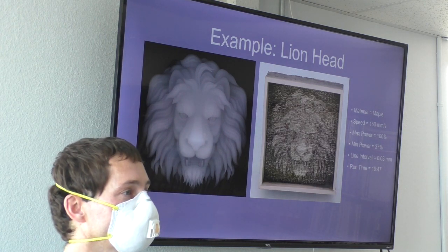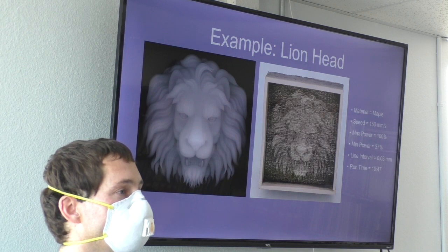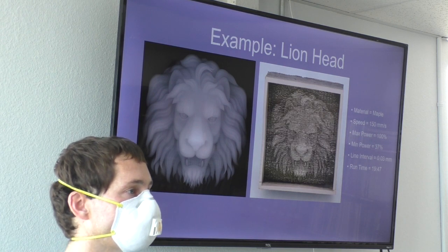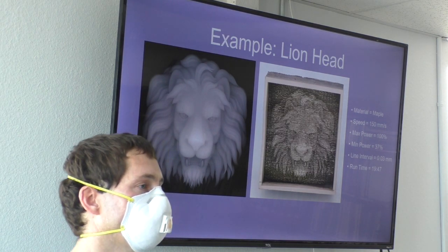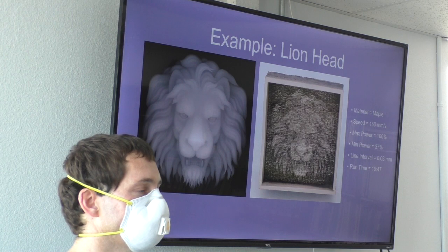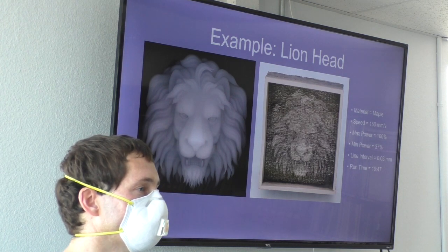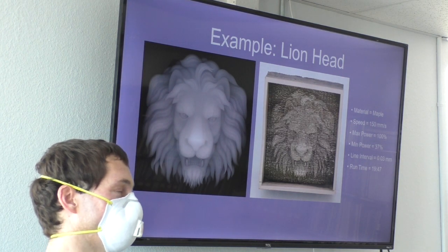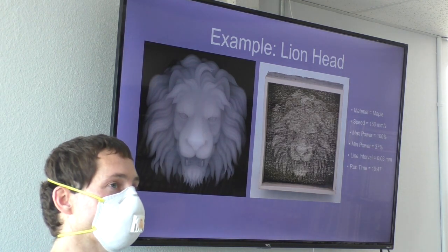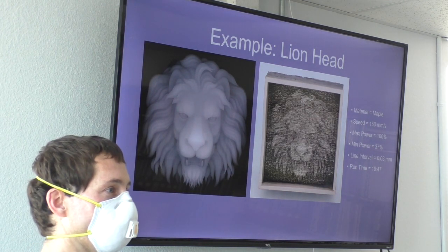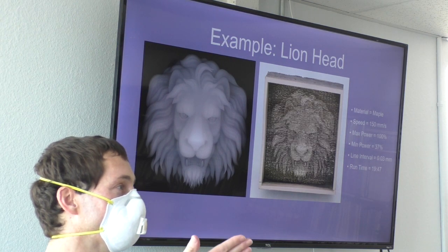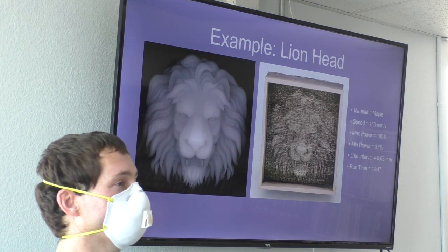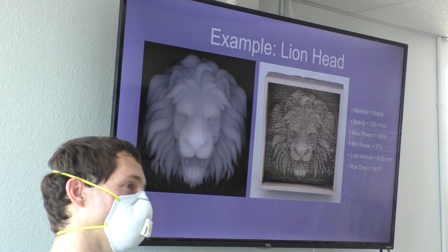Yeah. I tried cutting some 3/4 inch pine the other day, and as it happened, the grain was pretty much vertical, and it would cut very well through the summer wood and not through the winter wood, which you might expect, it's denser. Oh yeah, so that's actually another thing for the 3D engraver that I don't think I discussed here, but hardwood that's got very little variation in color of the grain works great. Softwood's going to be a nightmare. So as you found, pine in particular, the light color grain will engrave significantly deeper than the dark color, and you'll be able to see the grain in the surface of the cut.